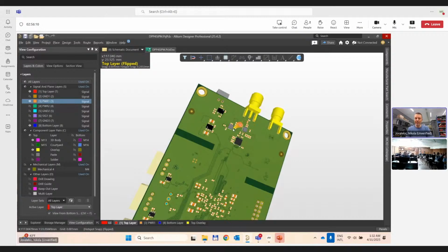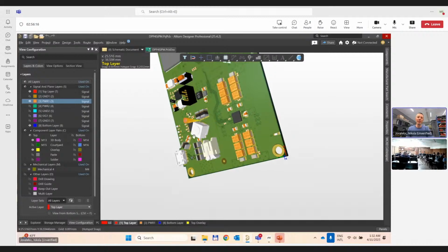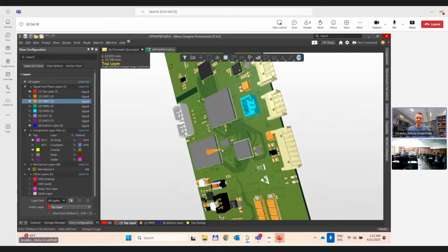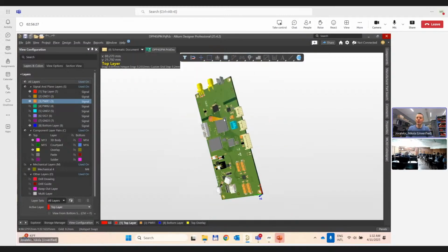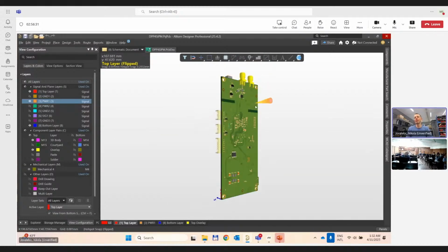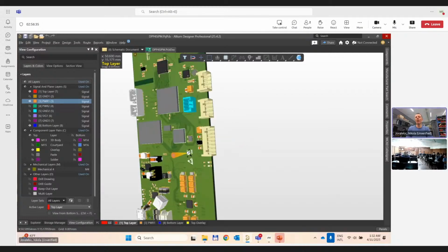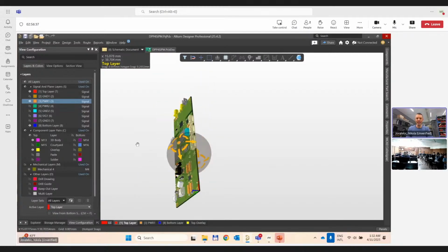You can notice that I put this in the bottom layer, and that the power supply and these components are on the top layer. I did that on purpose because there is a ground plane which acts as a kind of shield. So I want to decouple this even further by putting this on the bottom side. So this is actually how the PCB looks like.